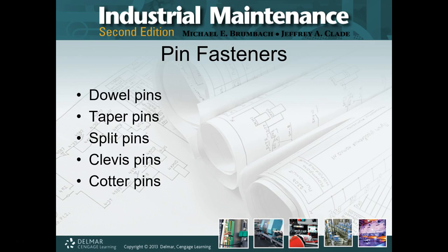They just literally position. Taper pins, on the other hand, are used to join and can be used to position, but they are used to join 2 pieces together, and you drive them in, and as they taper, basically you're using wedge force to keep the 2 pieces together. Not a big fan of them, but they're out there, and you've got to use what you've got to use. Split pins. Holy crap, you've got a full gamut of these things.